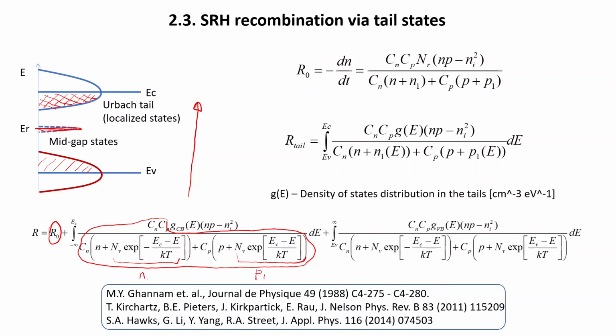And instead of NR, which we used as a fixed number of some recombination center concentration, we use here actually the density of states for these tails, which extend in the forbidden energies defined by the band gap. So when we have this distribution, it's either a Gaussian or exponential function which describes the distribution of these tails.